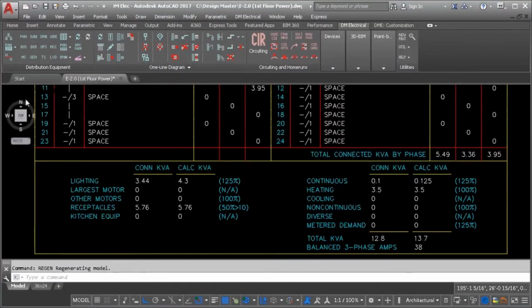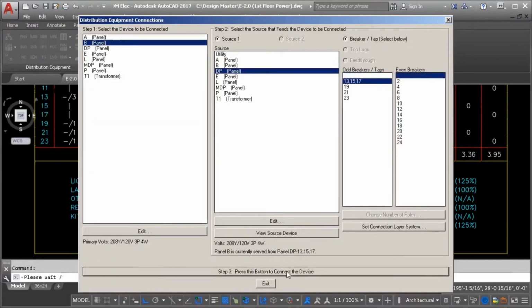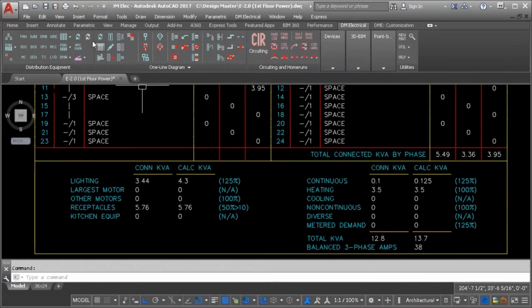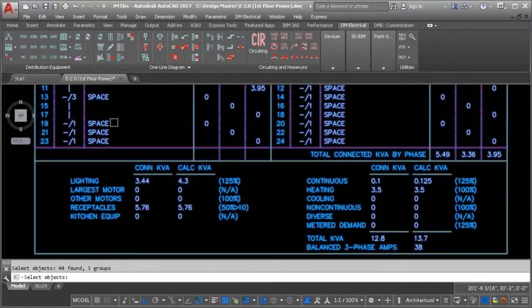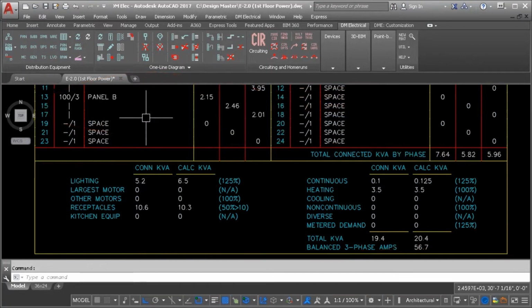The question after that is, can you do panel load calculations? Yes, you can do that. So this is where we're trying to be able to do feeder and service load calculations, basically NEC 220. And we can do that in Design Master Electrical. So all of those loads have load types. We can do the various demand factors for all of those load types on your panels.